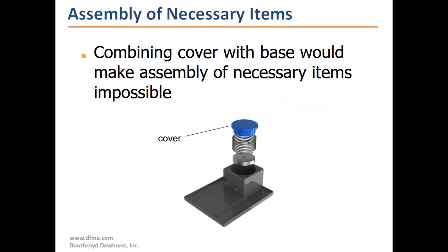So answering those questions is the key to the design for assembly analysis process. And as best you can, try to answer them literally. An important point to convey is that just because you can't think of how you would redesign your product not to have a particular part in it because it doesn't meet the criteria, it doesn't mean that you have to pick one of the ones that makes it meet the criteria. It means that you haven't thought of it yet, right? So DFA minimum part counts are generally low compared to the number of parts in a product, and we'll see that in the example that I have put together for you in a little bit.